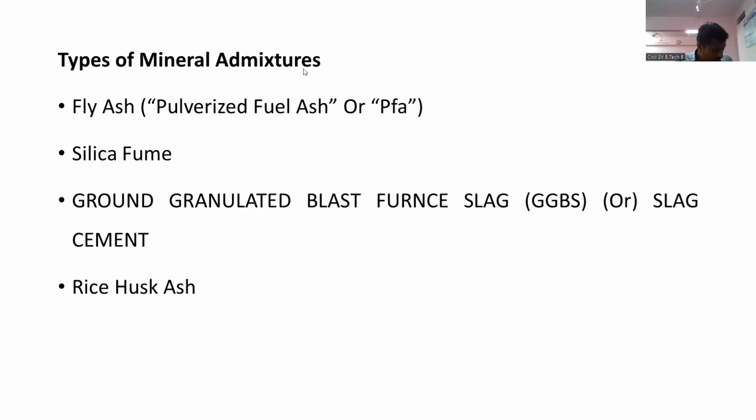Okay, suppose conventional brick, if you just go in the market and purchase, it is around 7 to 8 rupees, correct, for one brick. Okay, but if you are going to purchase a fly ash brick, it will just cost 4 to 5 rupees. Okay, and you just imagine you are going to save at least a rupee, a single rupee behind one brick, it is going to make a big difference, because in your project you are going to use thousands and millions of bricks, correct?